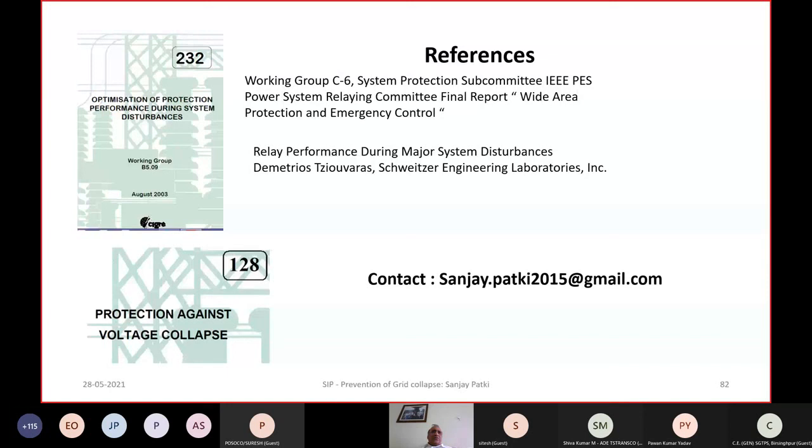So even if you execute tripping with a high speed relay which picks up in say 5 milliseconds, there will be another 5 to 10 milliseconds if you have many auxiliary trip relays, etc., and then there will be a 20 millisecond time delay. So overall interruption time will still be 30 to 40 milliseconds, which is sufficient for the sub-transient peak to get reduced, and then it should be safe for interruption of the breaker.